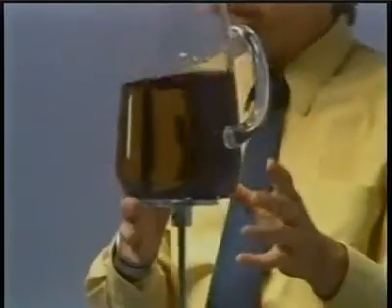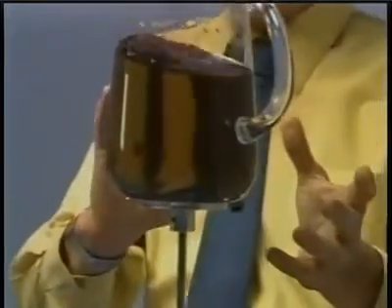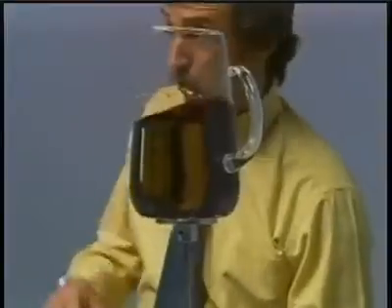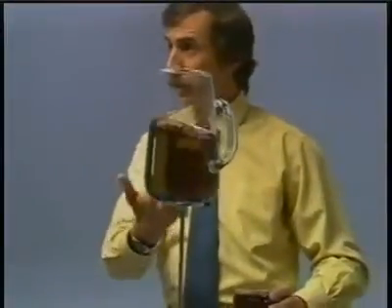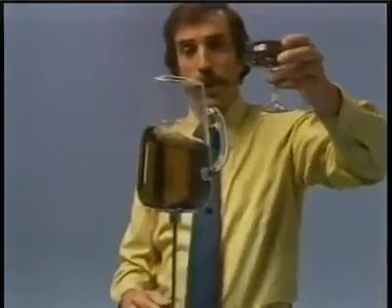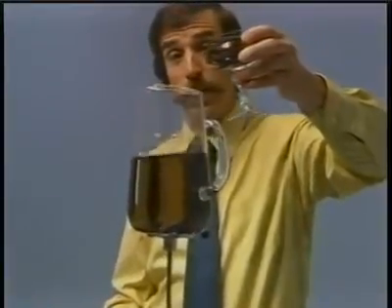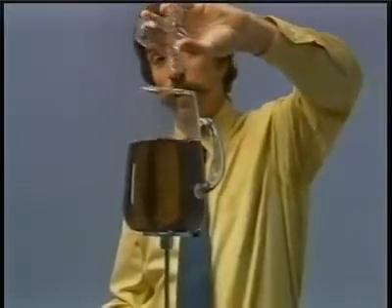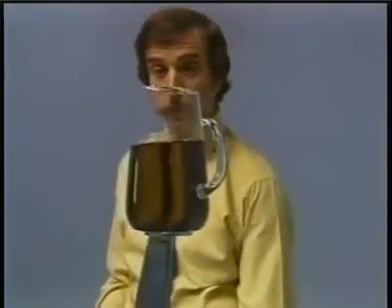Now, this is a fairly complicated system. The liquid is sloshing around. We, in fact, as you can see, have an instability right now, although it's controlled. And that's because the physics of the dynamics has changed. And we can put a little bit more mass into the system, and maybe or maybe not, that will cut down on the instability. Okay, well, in fact, what happened there is that we increased the mass at the top of the pendulum slightly, and that provided just enough damping to stabilize the system.